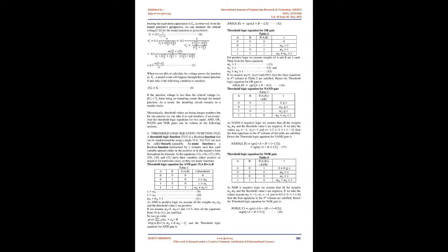2. Inverter. Almost every complex circuit requires an inverter. An inverter is depicted in Fig 1a, which is made up of 2 single electron transistors connected in series. The input voltage is directly coupled to the islands, indicated by small dots, of SET1 and SET2 through 2 capacitors, C1 and C2 respectively.